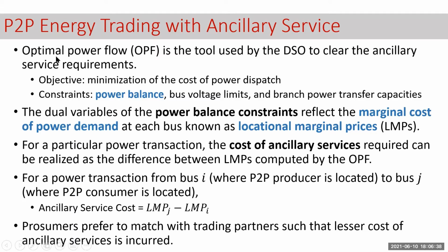One of the important features of this OPF is that, in mathematical form, there will be dual variables, since it is an optimization problem. These dual variables have a physical meaning. That is, the dual variables at the power balance constraints reflect the marginal cost of power demand at each bus in the system, depending on the power flow at which the OPF was executed.